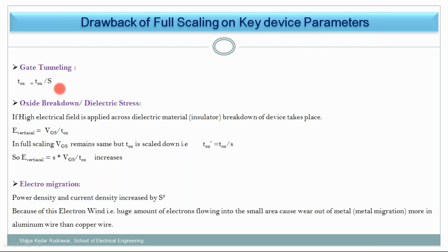Actually that gate current should not be there, it should be zero, because there is insulation, and because of that there is a high input impedance. Because hot electrons rupture the TOX layer and go through the gate, there is a gate current, which decreases the input impedance and damages the device. So that is happening because of this scaling.